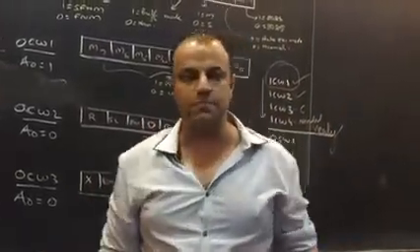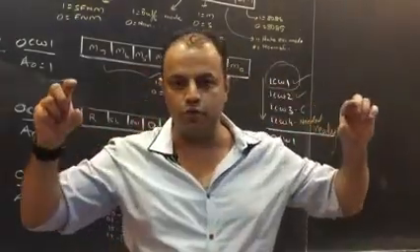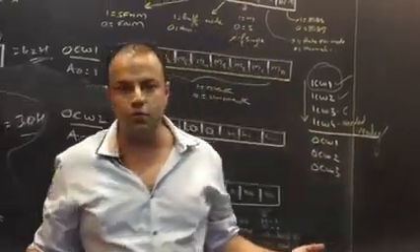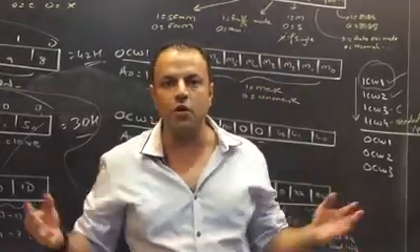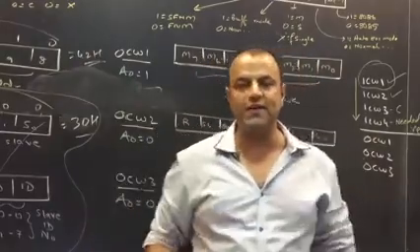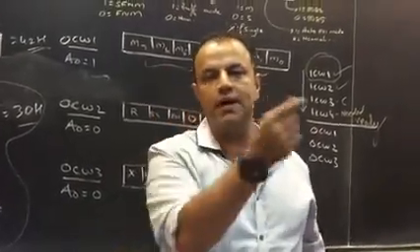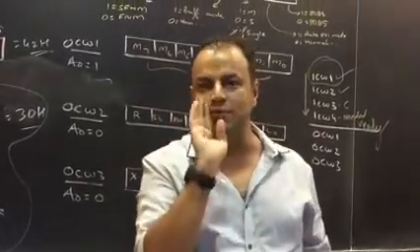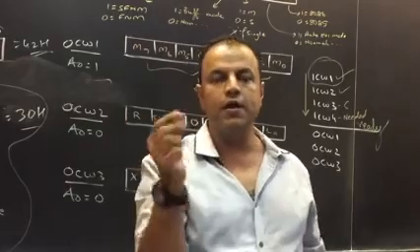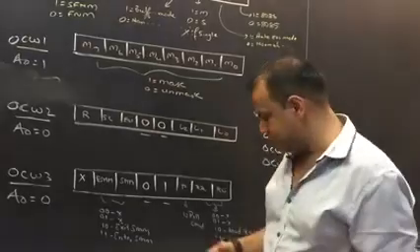So, let me put it very simply. Are you a smart person if you are giving ICW4 with all zeros in it? No, you understood that, right? Because giving ICW4 with all zeros in it is as good as not giving ICW4 at all, because that would have happened by default anyway. You're just wasting your time giving ICW4 if you want to give all zeros. So when do you give ICW4? When you want to make at least 1 bit 1. Did you hear me? Don't give an ICW4 if everything that you're giving is 0, because that will happen by default anyway. If you want to keep even 1 bit 1, give the ICW4 command. Tell me, are you clear? Now it will become more clear as we study the bits.